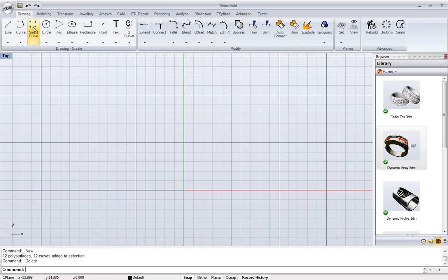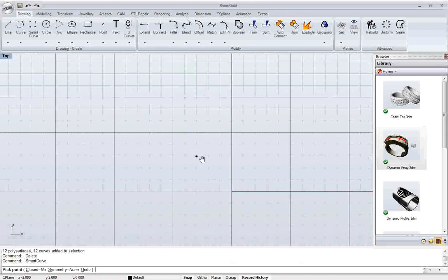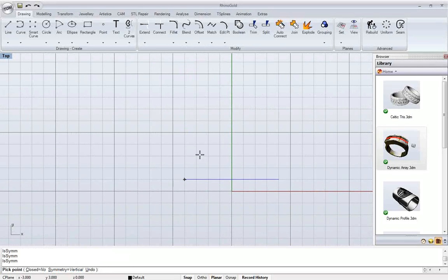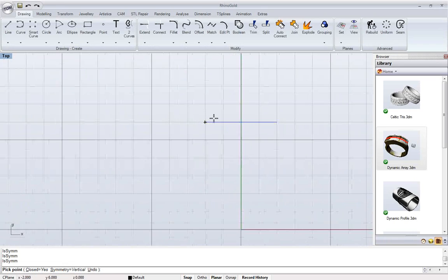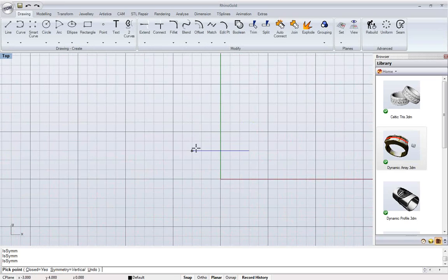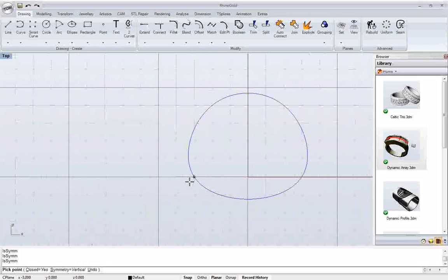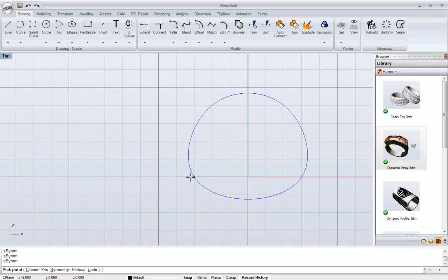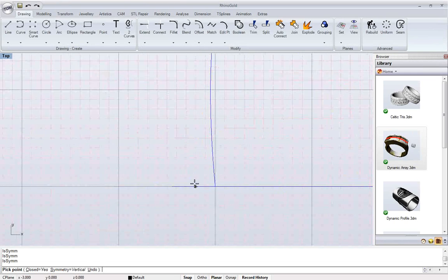And smart curve is one of these tools. This tool allows you to create symmetric curves. For example, I want to create symmetrical vertical curves. Close, yes. And take a look. Now it is 1 millimeter. If we zoom in, we have 0.1. It means, for example, I can click a point here. If I press shift at a corner, now the step is 1 millimeter, but we can zoom and say, okay, I want 0.6, 0.6,